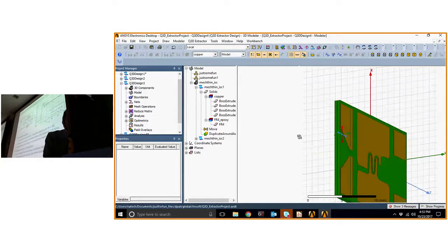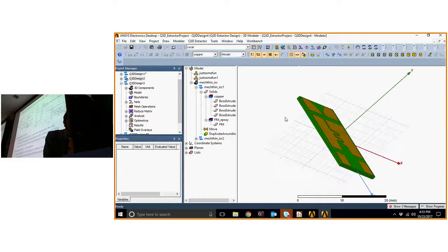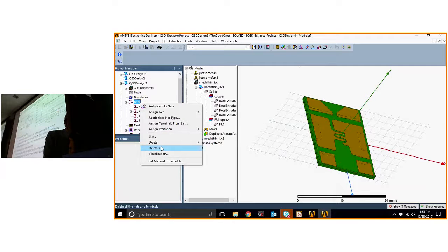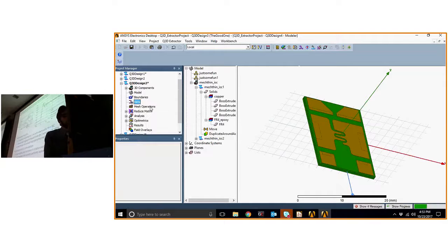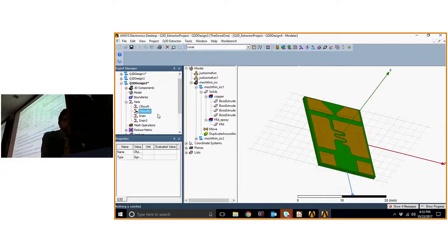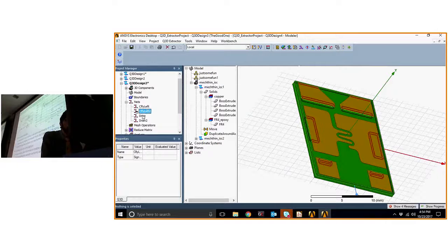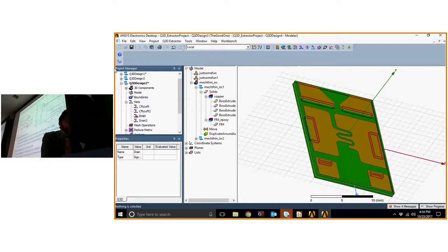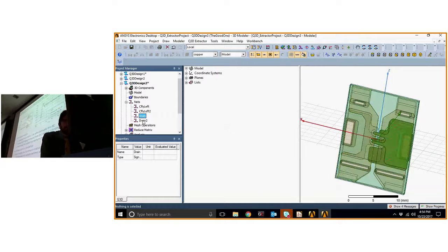Later, I can do it in that one, in this one we just had. So everything's pretty well set up mechanically. Now we just need to define our nets. Since these are all contiguous copper blocks, you can actually just do auto-identify nets. This is one of the most surprisingly functional features of this program, but I guess it's not highlighting them to show you. Oh, this is a different one. Okay. You can see that it determined these are indeed your nets because they're made out of copper.